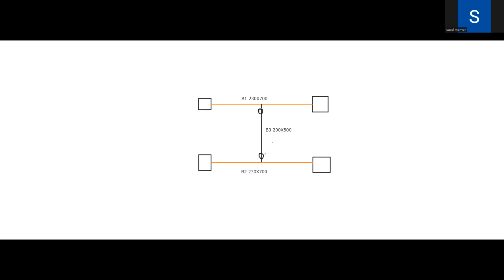It will act as a beam supported by a pin joint. As we have studied in SFD and BMD, for the pin joint we have a bending moment of WL square by 8. So this same condition will be generated over here as WL square by 8. This is basically why we are providing the releases.